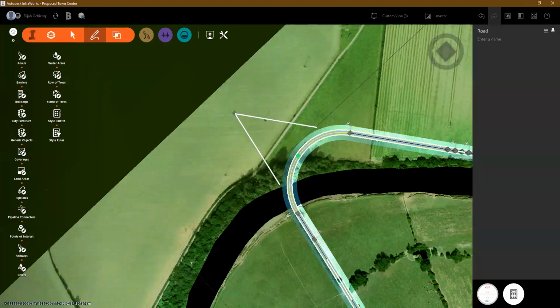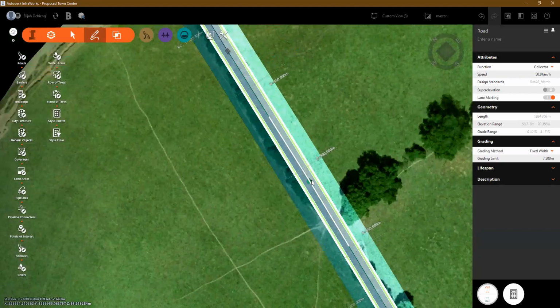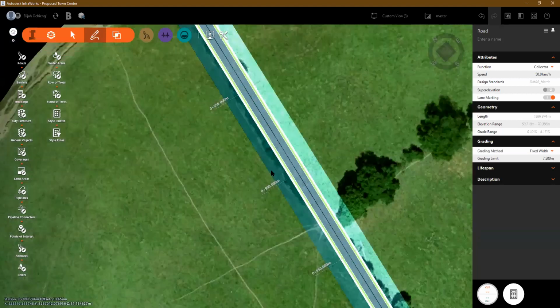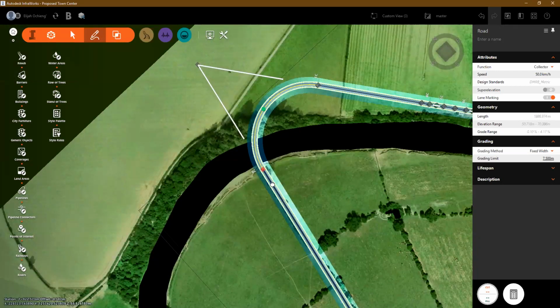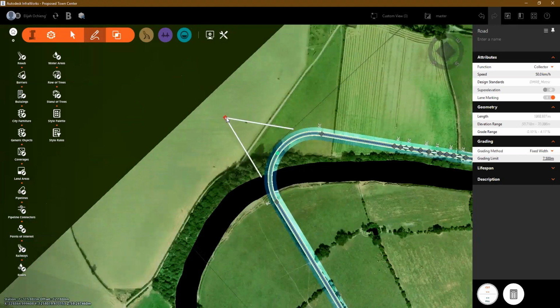So maybe I also don't need this curve at this particular point. So I'll just select and remove it. I only need one curve towards the end of the straight. So then after that, I'll be able to adjust this. So you can see immediately it reaches a value which is greater than the minimum. You can see now I'm no longer having the yellow color. So if I slide it lower, you can see it turns green. That means that I've specified a value of the curve which allows the vehicle to turn there or to maneuver within that curve without the danger of toppling.